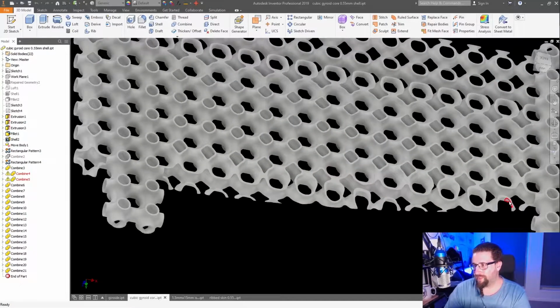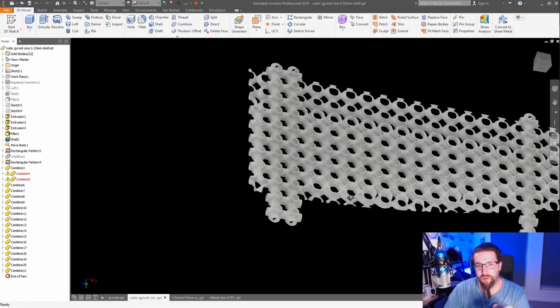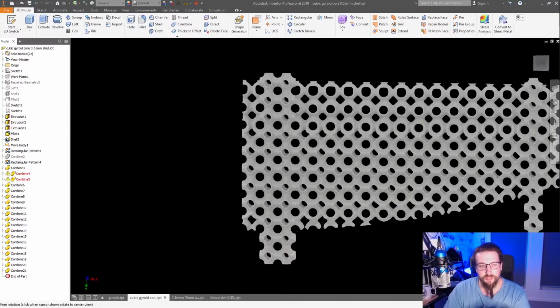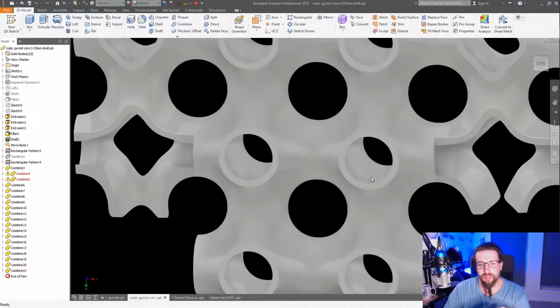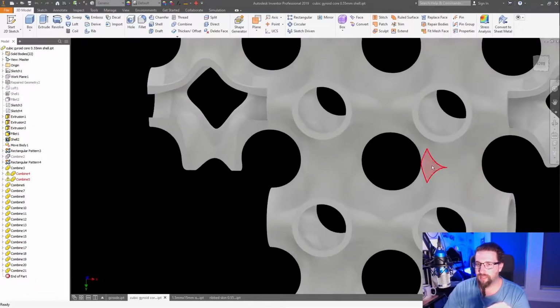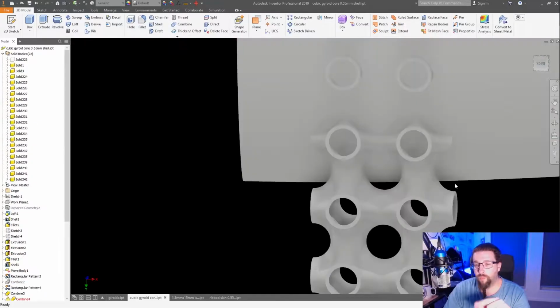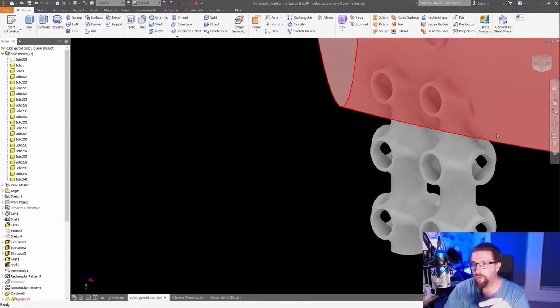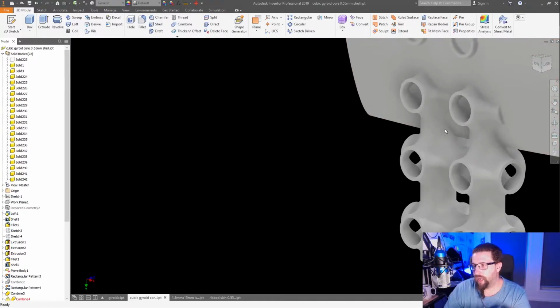This you can model up. This is easy to pattern. You can see for the most part the Boolean works. For some reason in these sections here, and I believe it has something to do with the pattern intersecting this line here where this block and this block meet, even though this is a solid object, when it goes to do the intersect for the wing skin surface through this area, something about it doesn't like it, and it won't do it.